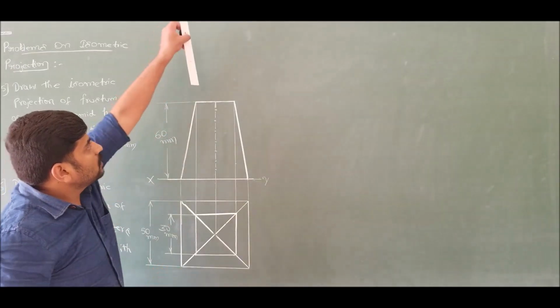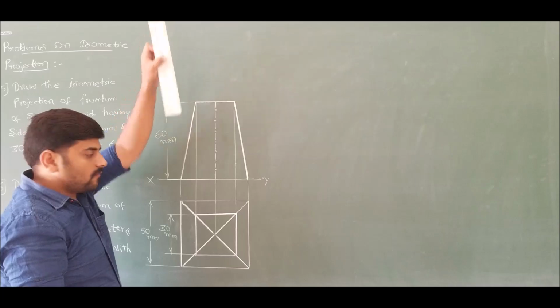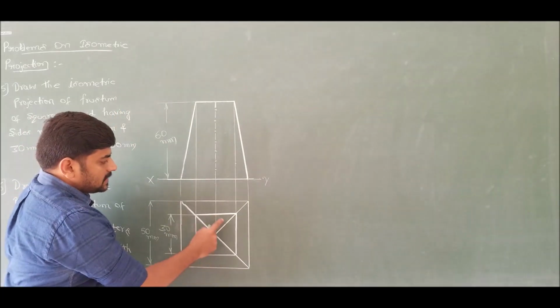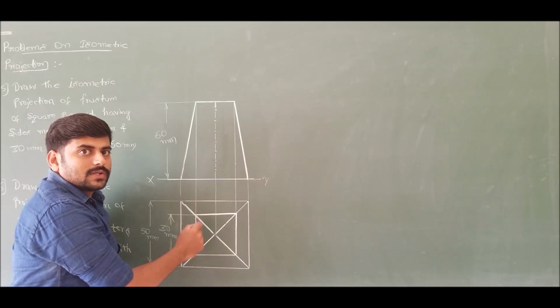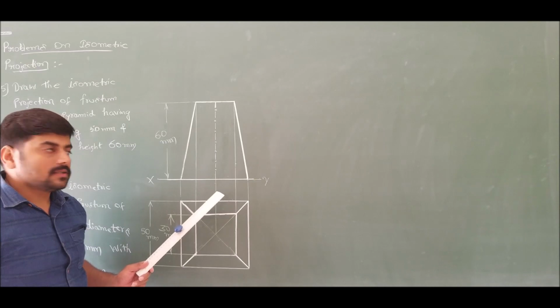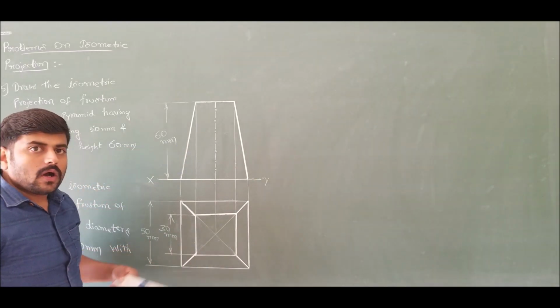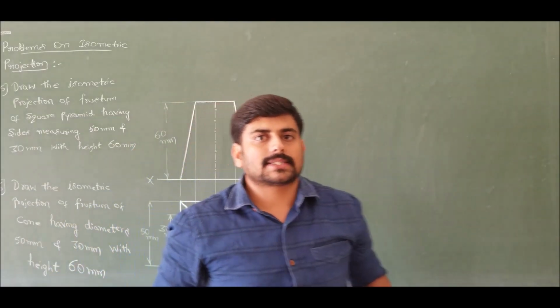Now in the top view, if I view this pyramid, I will see a hollow space. Therefore, erase this inner triangle faces. If I do that, this completes the required front view and top view of the frustum of the square pyramid that is asked.